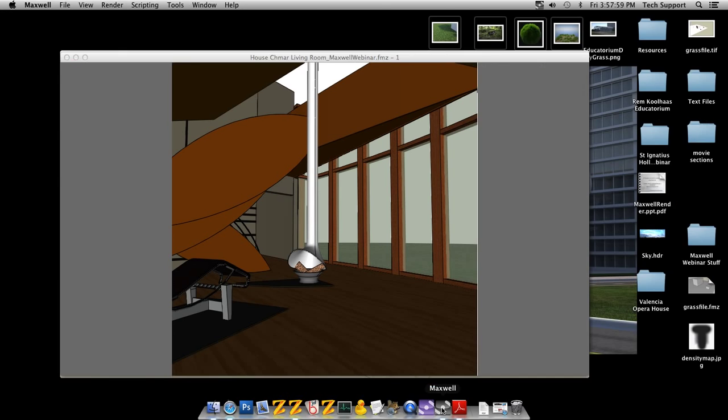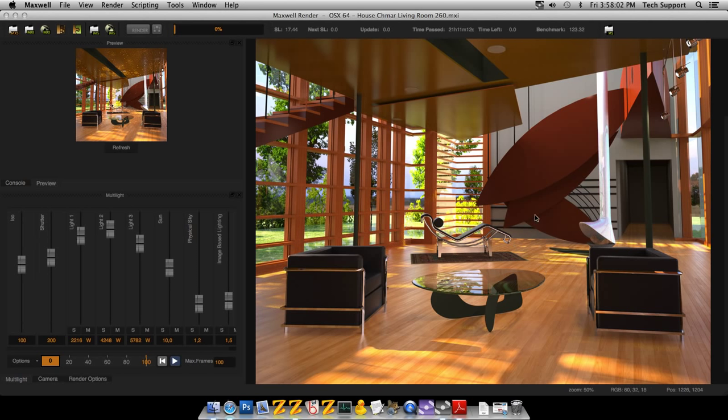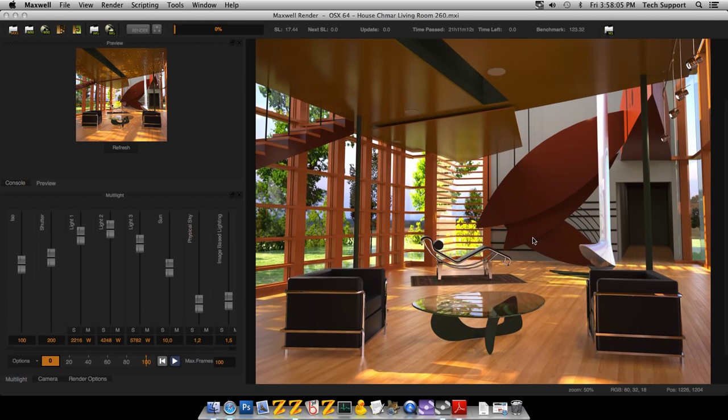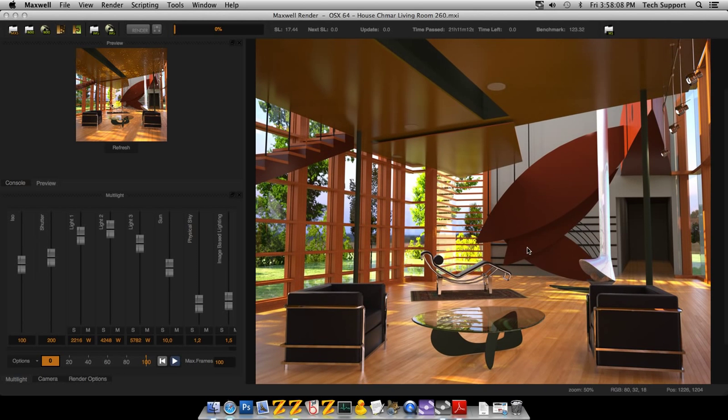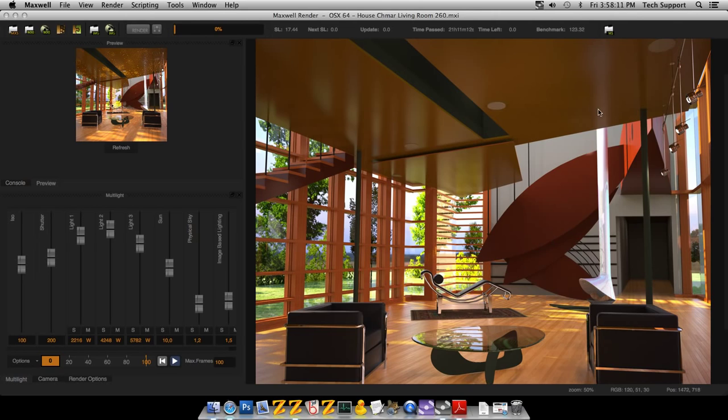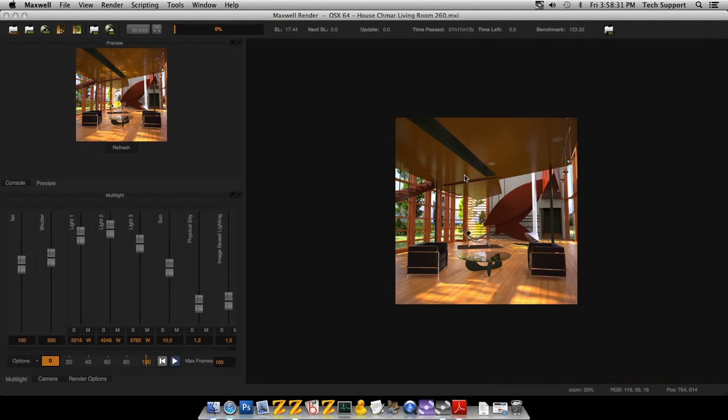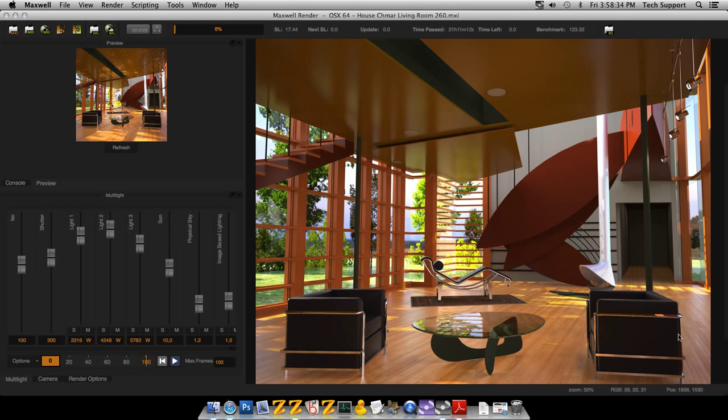So let's go ahead and look at what happens here in my image. Now, I've used all MXM materials in this particular image because I wanted to really get as close to realistic as I could. And Maxwell is incredibly great at doing this glossy reflection thing. In fact, many surfaces in real life have an element of glossy reflection, whether it jumps up and hits you in the face or not. It doesn't matter. Your mind is sort of expecting to see some type of glossy reflection on there. Very few surfaces are actually matte. Here on the floor, you can see this very subtle glossy reflection here that really makes the floor look very realistic.